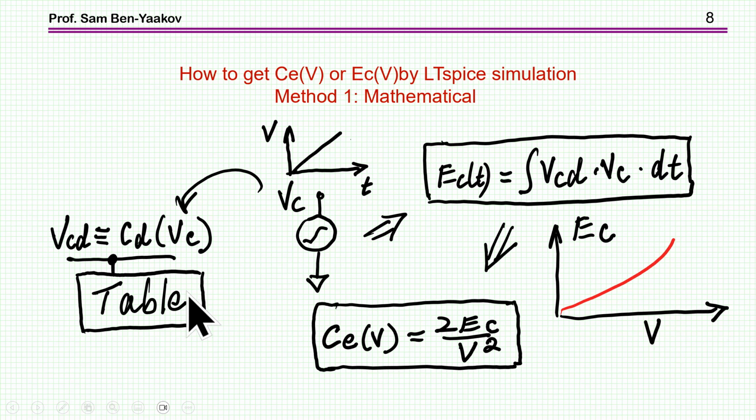So the trick that we are doing is coding the capacitance into voltage, creating a voltage which is numerically equal to the capacitance, so we can then handle it as a variable in the simulation. So the first stage is to generate this table and then to have this node which has a voltage equal numerically to the differential or small signal capacitance.